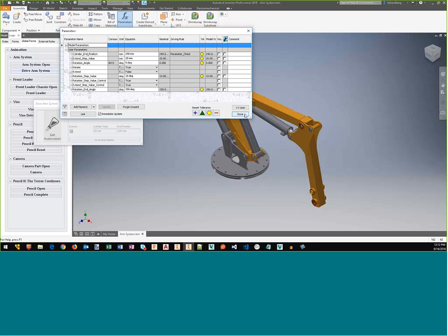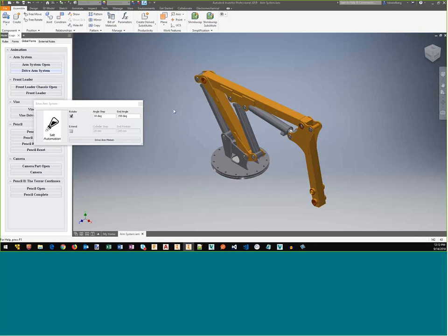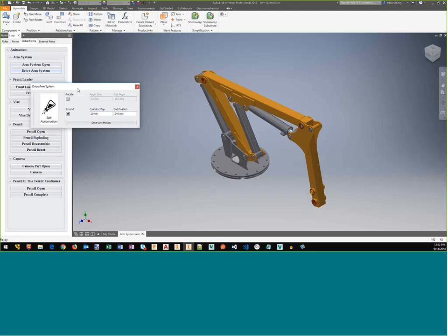That was primarily done just for simplicity's sake. Those of you that have done iLogic development understand that the base units inside of iLogic are in centimeters, so that Randy didn't have to go through a conversion process to convert all of his values back and forth. He simply kept everything in a metric format.